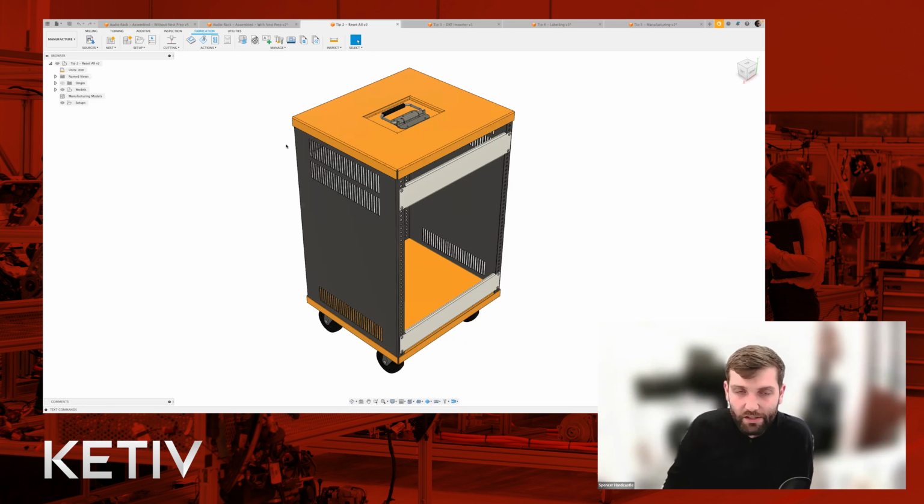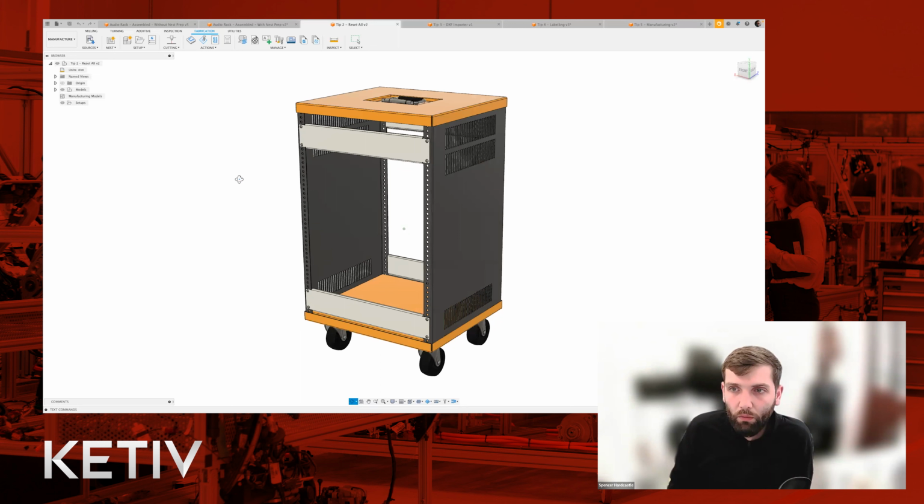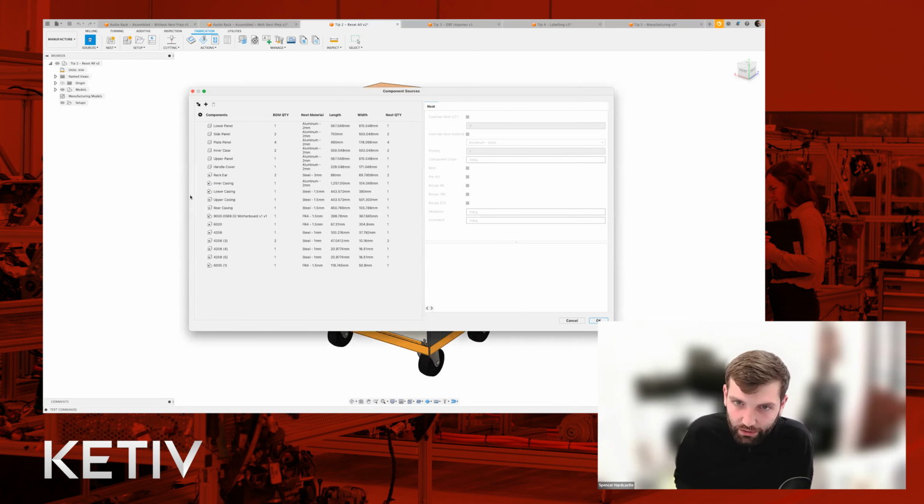Nesting's a complex process. There's a lot that can go wrong, whether something happened to the translation of the file. What I mean by that is when it starts to calculate the nestable shape, the 2D flattened geometry, it may get itself a little twisted. Maybe you've gone in component sources and you've changed a load of things, made some changes to quantities and to various different models.